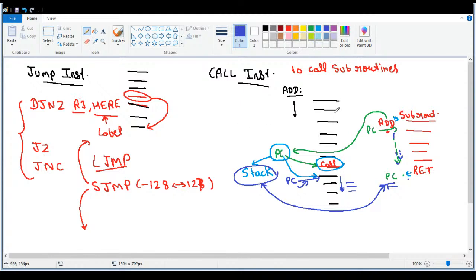Let's say the stack pointer denotes 07 in the RAM. It will become 08 after putting some address into it. Now 08 is register R0 of register bank 1. So if in this entire program you are modifying the content of this R0, then your program will go haywire, meaning it will stop working.